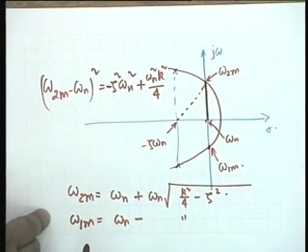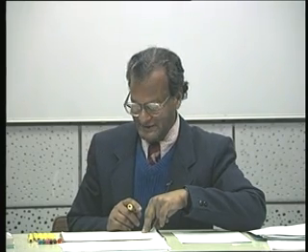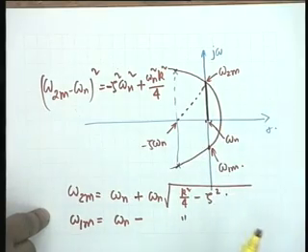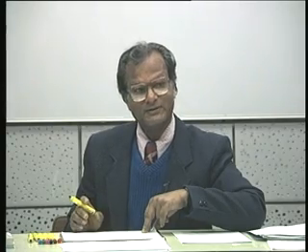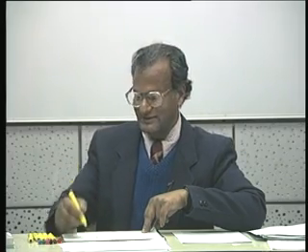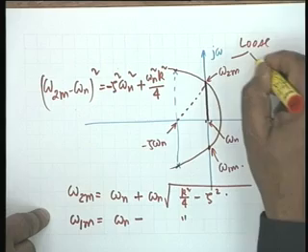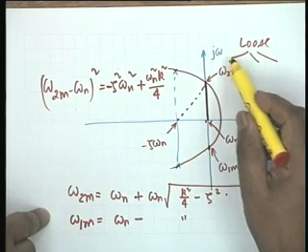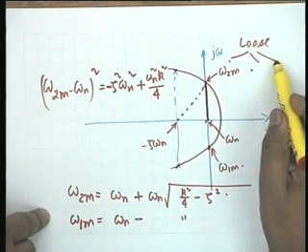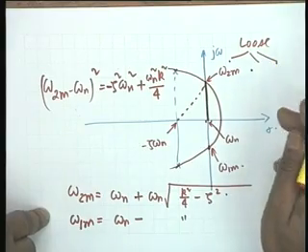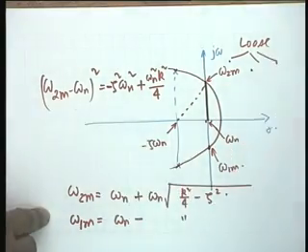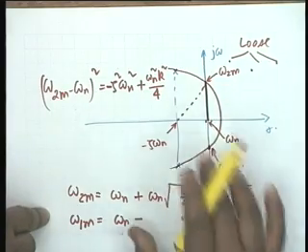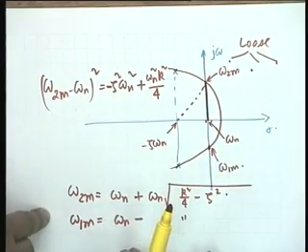One must not lose sight, however, of the assumptions. Assumptions were that the damping was very small and the coupling was loose, but at the same time double peaking occurs for the over coupled case, over coupled under loose coupling. Loose coupling has 3 stages: under coupled, critically coupled, and over coupled. Now over coupling may be increased to an extent that all these assumptions go down the drain. Then none of these expressions will be correct.